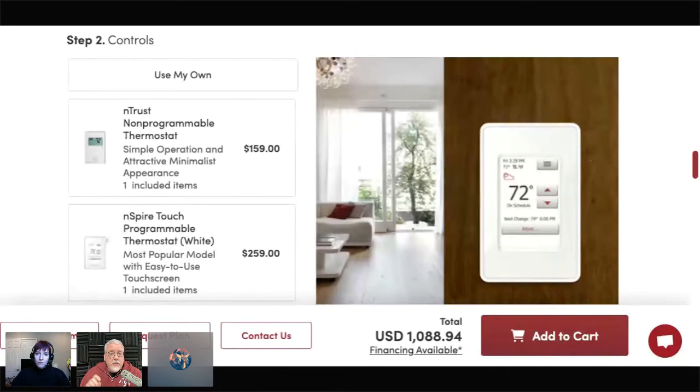Also, when you're choosing these third-party thermostats, these control room temperature. A lot of them have no floor sensor. Very, very few have a space for a floor sensor to go in. But why that's so important is because if you're using laminate, LVT, or carpeting in the USA, those have a temperature requirement. You can't go over a certain temperature. A Nest has no way of knowing what the floor temperature is.